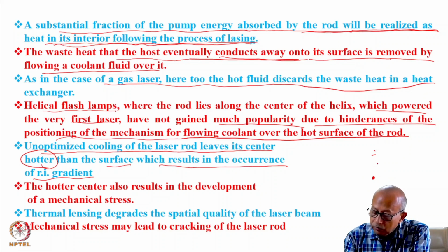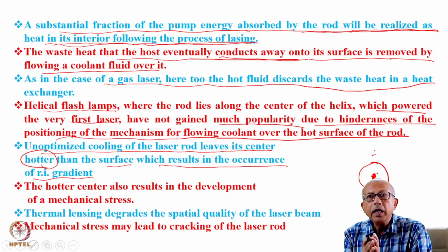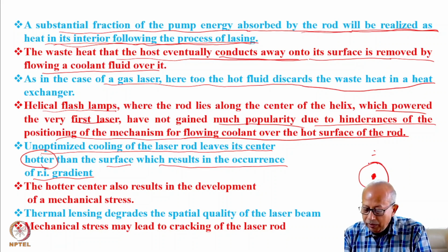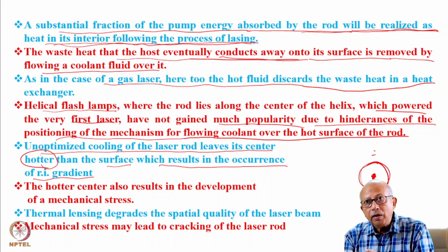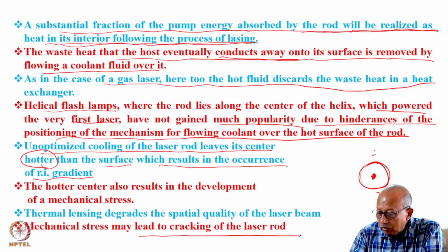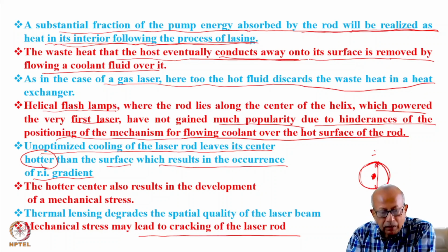You see, this is your laser rod cross-sectional view. The center will be hotter and the edges will be cooler. So the central region of the rod will be expanded more, and the edge will be expanded less, because its temperature is less. So that will develop a mechanical stress, which may lead to even cracking of the laser rod because of uneven expansion across its diameter. So these are the issues.